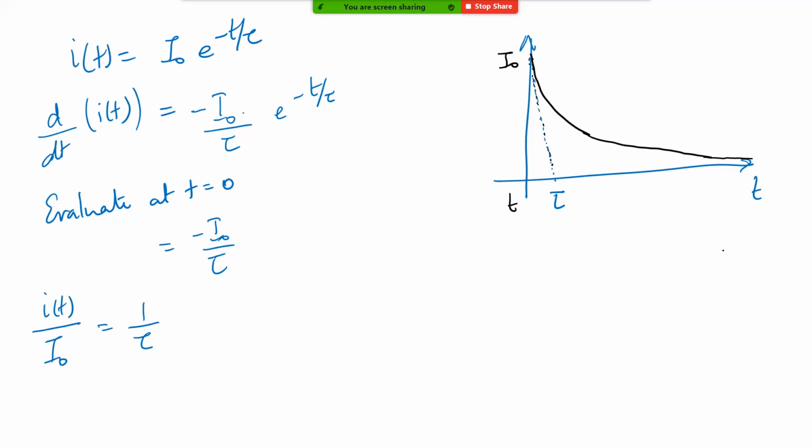So that is basically not going to happen. But if you are looking at the rate of change of current or voltage at a time close to t equal to 0, in some cases you might be interested in the rate of decay. Correspondingly, if you want to look at the inductor voltage, it will be L di by dt.